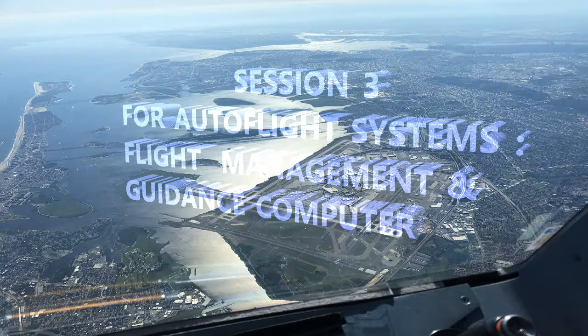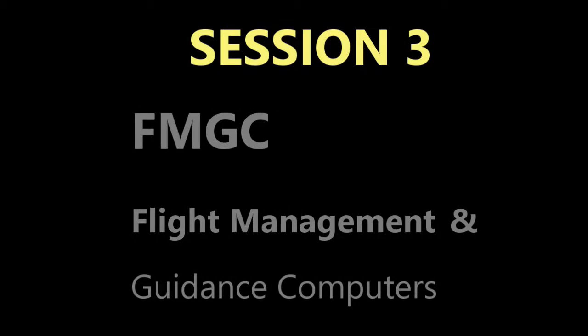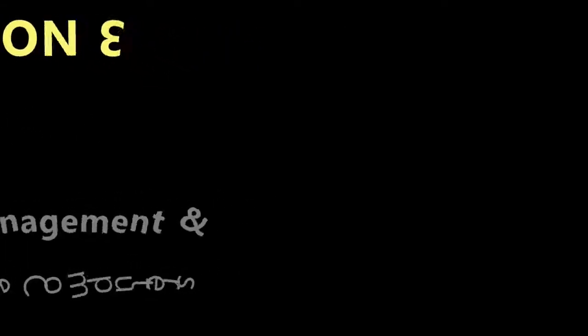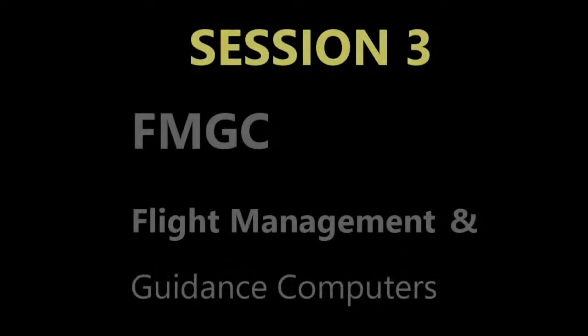All right. Okay, so let's start with the engagement push buttons. What kind of buttons can we expect to see here in this FCU? So here you've got different push buttons. You've got actually a total of 6 push buttons, and just from left to right as you look at it dead on, you're going to see the localizer engagement push button, and then just continue on that horizontal line of view. The one next after is your auto thrust engagement push button, and then after that you have your expedite engagement push button. Now the expedite may or may not be there. It's an optional function, so just keep that in mind. Then you also have your APPR, your approach engagement push button.